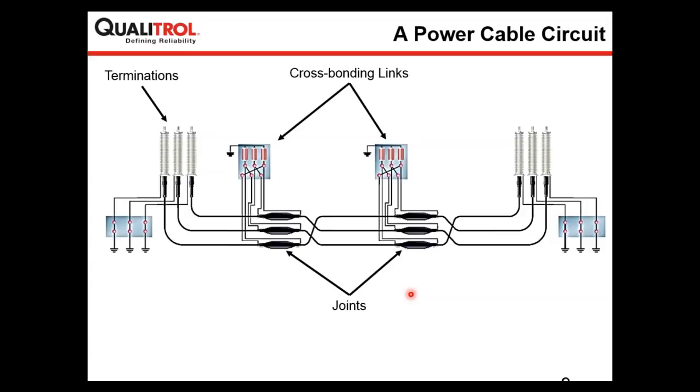If you contact us later on, we can give you the literature or discuss in detail how to perform this return time measurement and how to accurately get the PD pulse propagation speed. Based on the cable length, the propagation speed, and the time difference between the main and reflected pulse, you get a very accurate location of partial discharge from the measurement end.